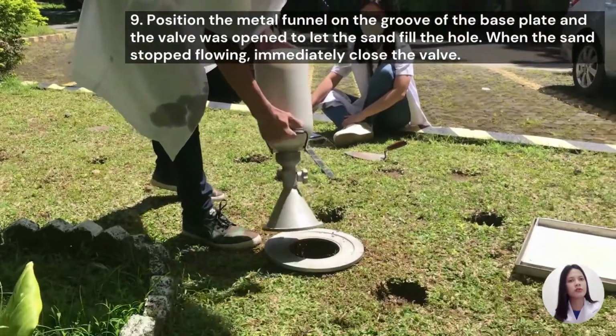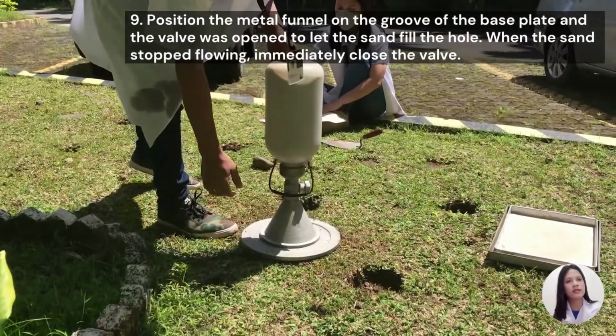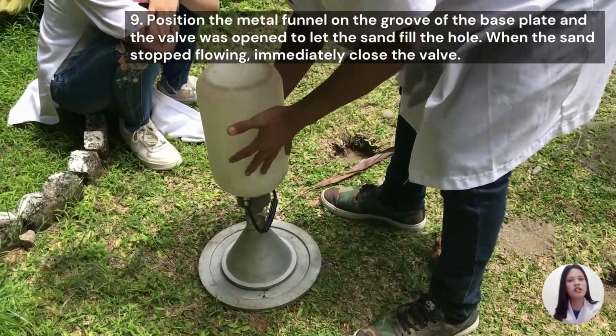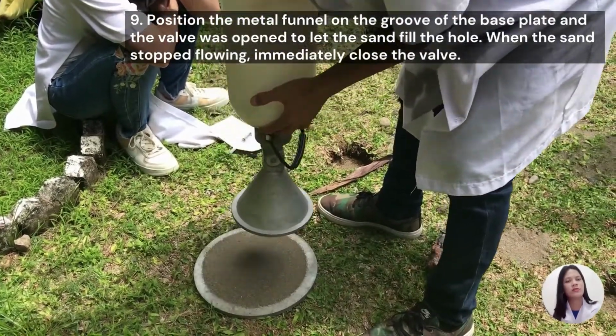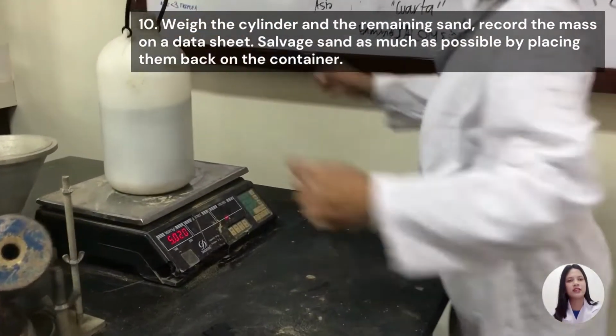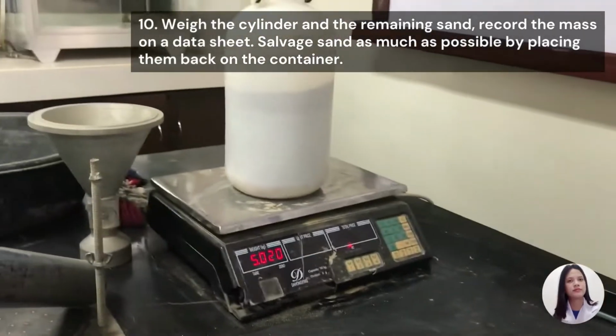Position the metal funnel on the groove of the base plate and open the valve to let the sand fill the hole. When the sand stops flowing, immediately close the valve and remove the apparatus from the test hole. Weigh the cylinder and the remaining sand. Record the mass on a data sheet.